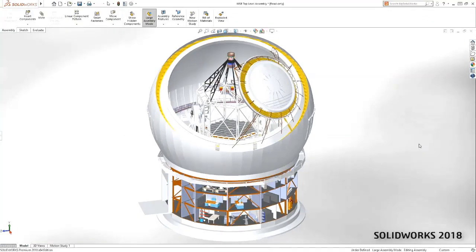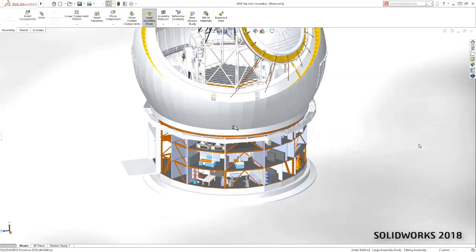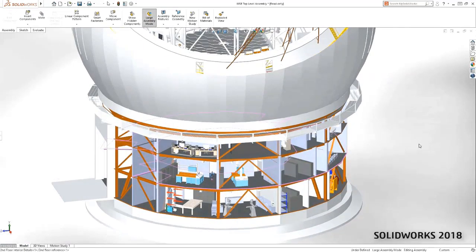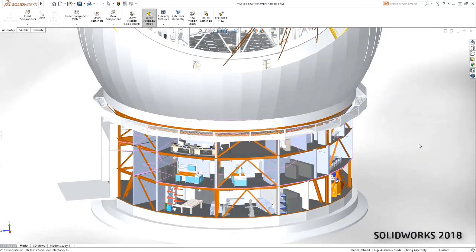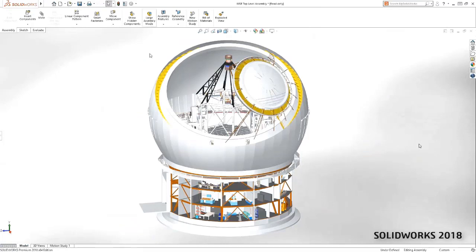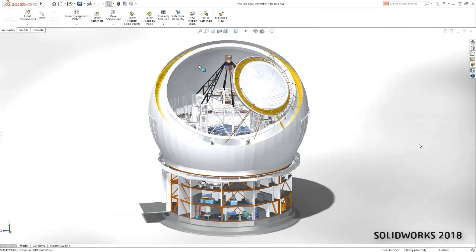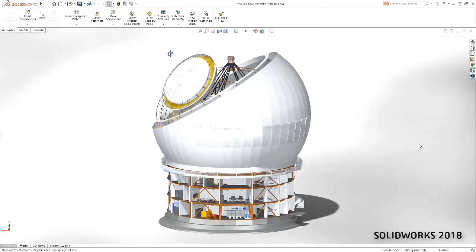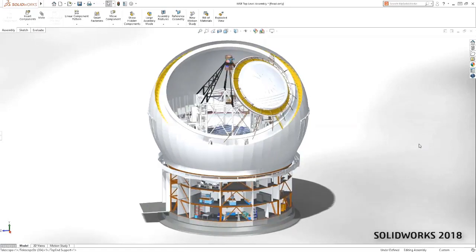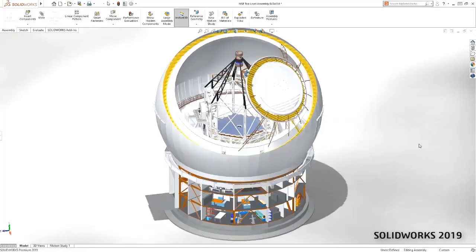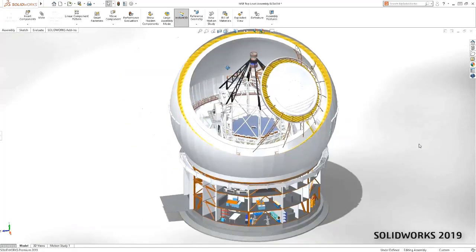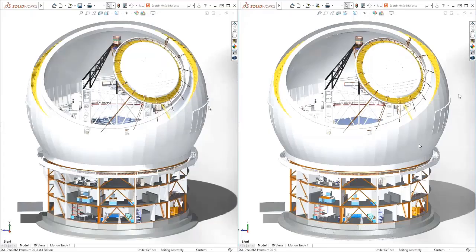Over the years, SolidWorks has worked hard to optimize view manipulations on the screen. For instance, large assembly mode will disable mono edges, shadows, real view, and more. The level of detail is set to fast, which removes small components during view changes. These optimizations make view manipulation fast, but come at the expense of visual appeal. When better visual quality is desired, large assembly mode can be disabled, but graphics performance is sacrificed. SolidWorks 2019 changes the game. View manipulations are lightning fast, even with large assembly mode turned off. In a side-by-side comparison, you can clearly see the improvement.